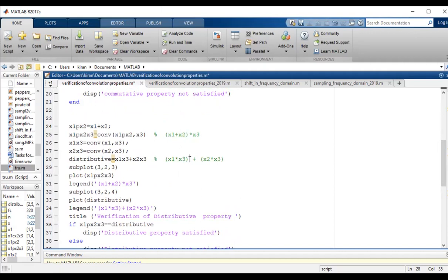So what they say is the distributive property says that you think clever, you add them first, then you do the convolution. You can reduce hell lot of multiplications and additions. Okay, so that is the importance of distributive property, and of course convolution satisfies this particular distributive property, right? It's a cool property, I guess, because it saves you lots of time and power.